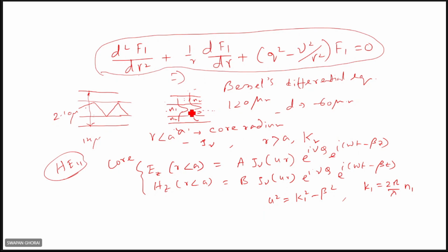And if you examine this one, there is a peak at the middle, and there is a decaying field at both ends. You see some decaying field is there, right? That is called the evanescent field, evanescent wave, right? Exponential decay is here, that is the evanescent field. That is electromagnetic wave theory. So for each mode, there will be an evanescent field in the cladding.